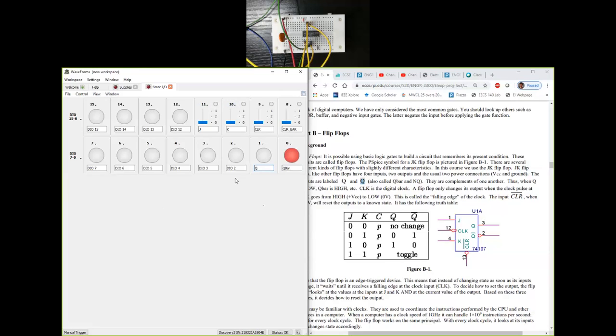You could have selected any 4 from the 16 options. I have connected them in that particular sequence because it's more comfortable for me. And then I've configured them as push-pull switches. Q and Q bar are outputs of the chip, available on pin number 3 and 2 of the IC, and I've connected them to channel 0 and channel 1, indicated by colors pink and green on the analog discovery pinout, and I've named them appropriately.